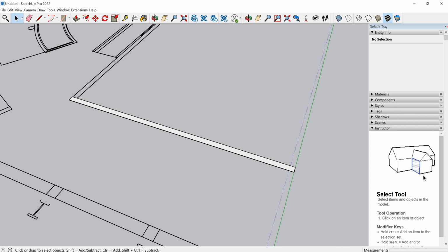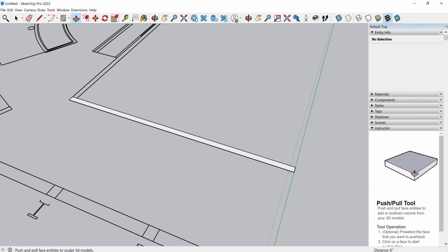The way that I draw in SketchUp, I'll have these interior lines that don't mean anything, and I don't want a division of the actual wall in this case, and so I'll just clean it up. This now becomes one shape. How you know it's one shape is because it's shaded, it's that lighter gray, and then this allows me to grab pretty much push and pull.